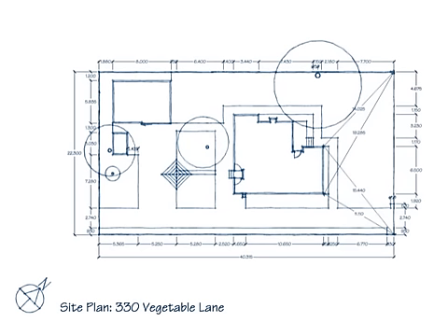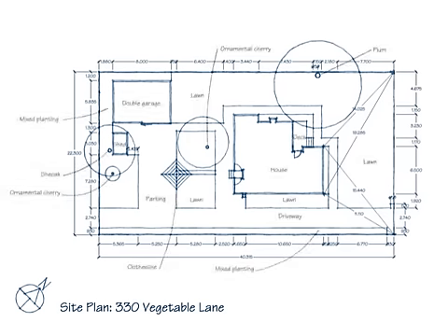In this example, we were able to confirm that the site was rectangular by checking the surveyor's plan on the certificate of title. We did use multiple measurements to check that the house was located on the section parallel to the site boundaries. The last thing to do is add notes about the key features of the site, such as buildings, existing garden areas, large trees and shrubs, and hard surface areas. Your site plan is now completed.